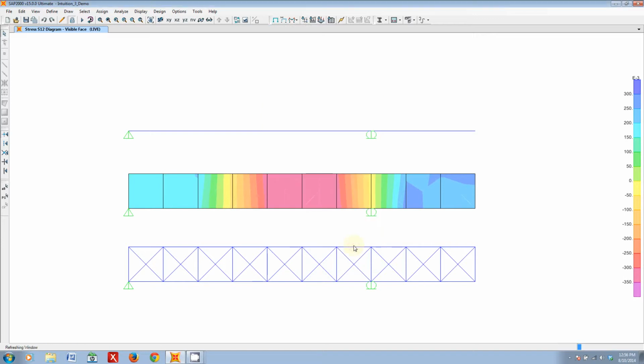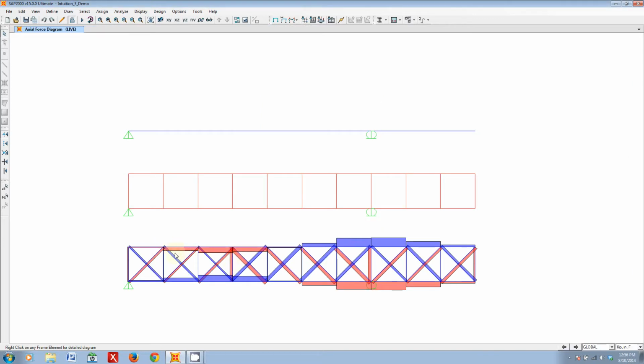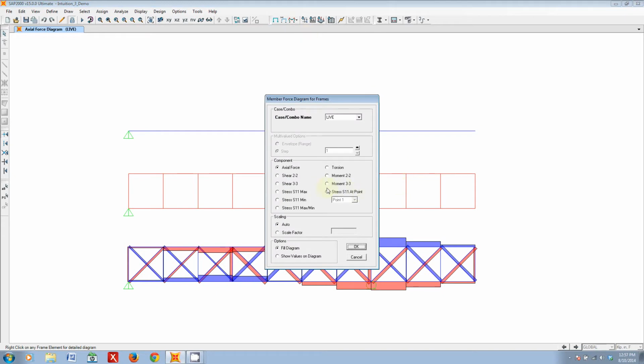Let's go to axial. Alright, so that means pretty much in this region, constant shear, and then it changes signs. So tension going down, now comes up, and it's constant again in this region. And then it changes sign again. So tension going up, now comes down, and then it's constant for this last region as well. So everything is working out perfectly. I couldn't have planned it better.